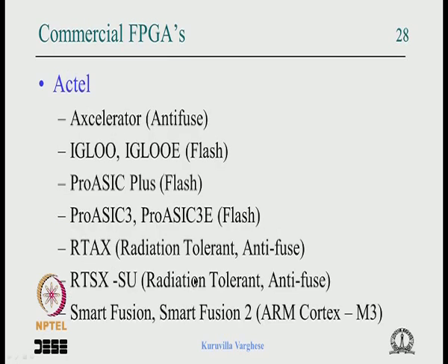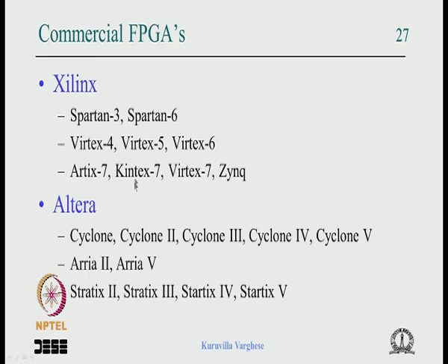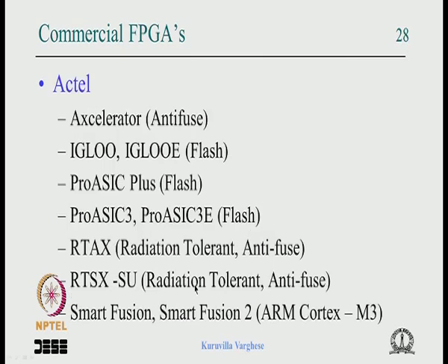Actel is different. All these are the static RAM based FPGAs, and when it comes to Actel, another manufacturer, it has devices like Axcelerator and RTAX and all that, which are anti-fuse based, and there are flash based ProASIC, and there is SmartFusion with an ARM Cortex M3 built in as a hardcore with this Actel.